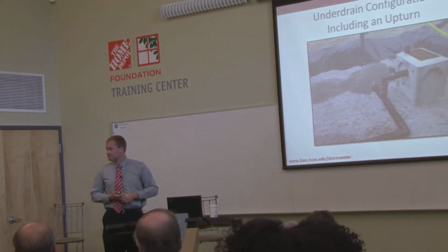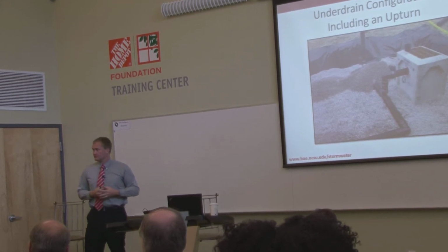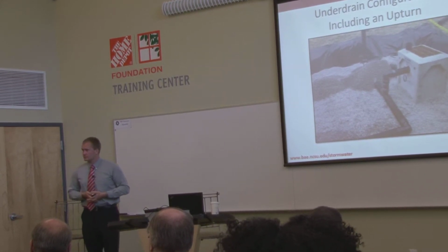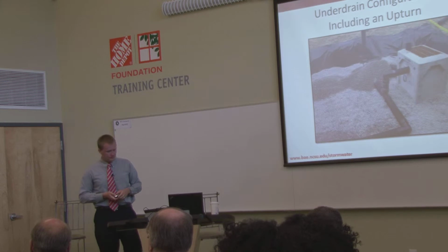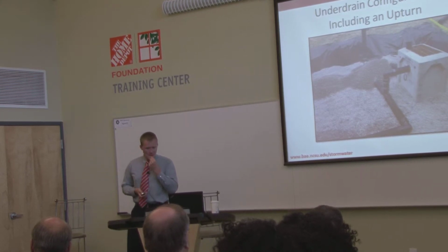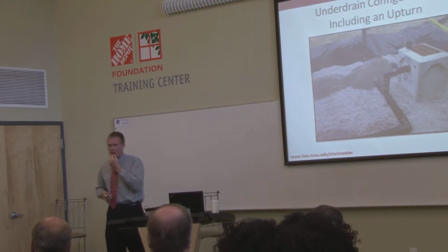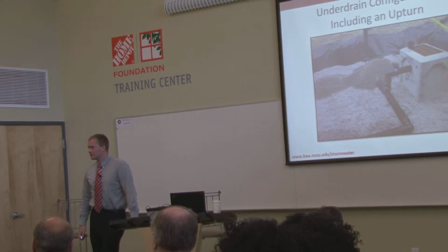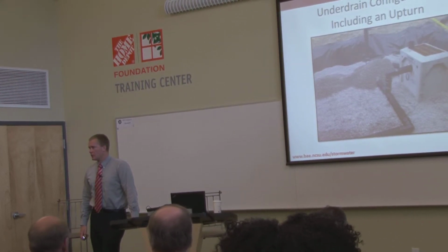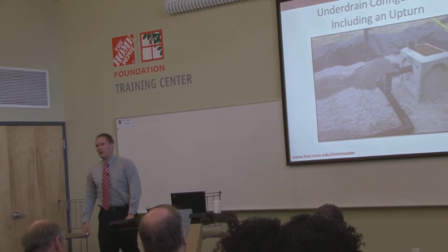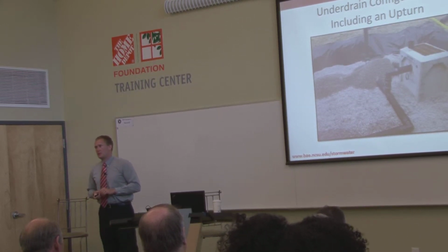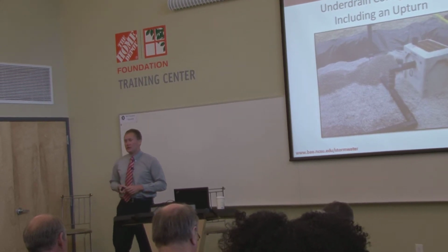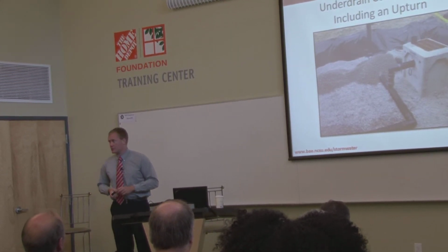One thing to mention, the design manual does say 0.25 inches per hour infiltration, but we recommend underdrains on every bioretention. Just during construction, compaction happens, and we'd rather have a conservative design, have overflow. I mean, I can't imagine underdrains would be more than 5 or 10% of your cost. The media is really the large portion of the cost.